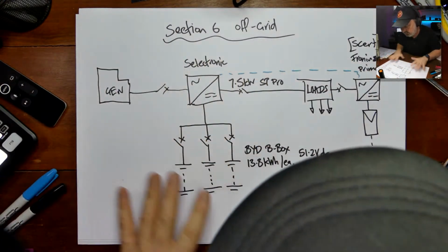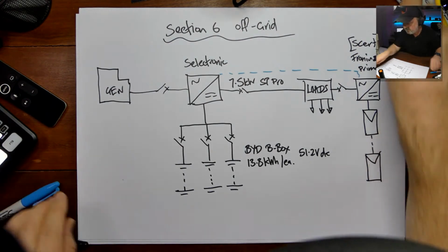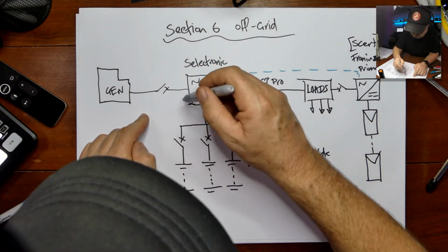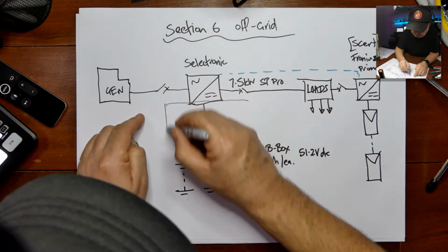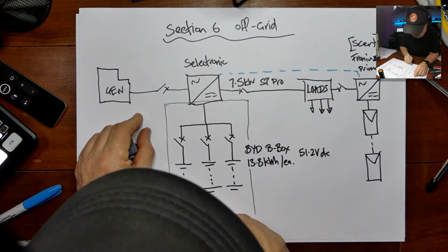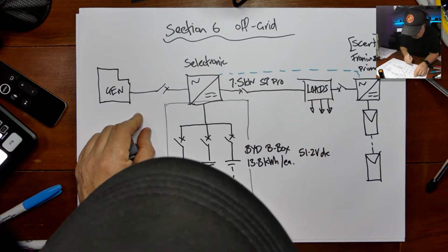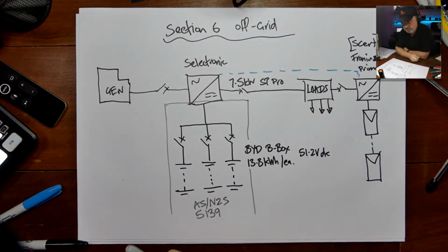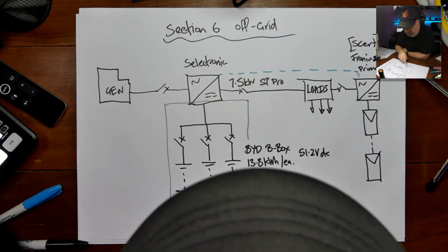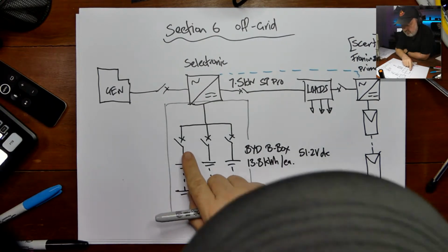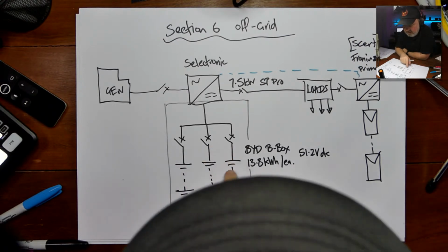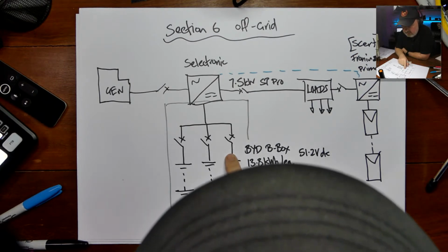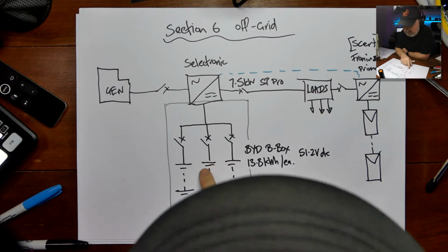Now, where does the battery standard apply to all of this? It applies to areas such as right up to the terminals of the PCE, right up to here. This area here is covered by AS/NZS 5139. And one of the things it states is that with parallel strings of batteries, and we've got 3 parallel strings, you need overcurrent protection in each string, and you need to be able to isolate, in a readily accessible location within 2 meters of the battery system, each of the battery modules.